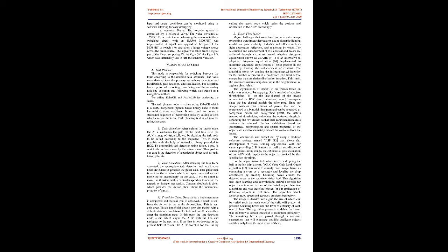1. Task detection. After exiting the search state, the AUV continues the path till the next task is in the AUV's range of vision, followed by deciding the task node to be called according to the sequence. This is made possible with the help of ActionLib library provided in ROS. To accomplish task detection using action, a goal is sent to the action server by the action client. This goal in our case is the detection of a particular object such as path, buoy, gate, etc.